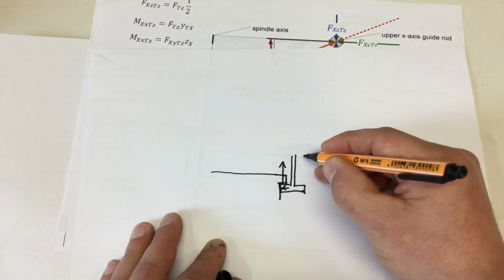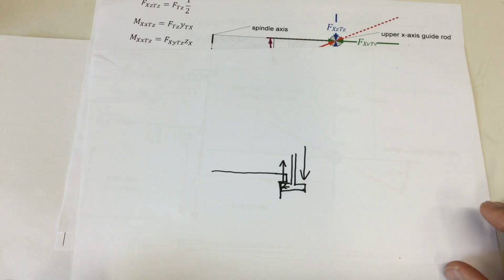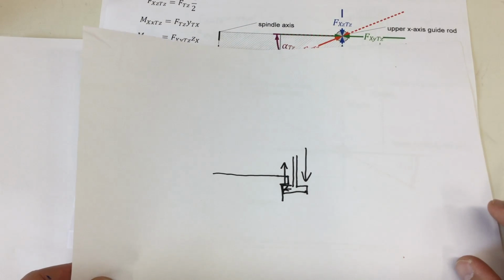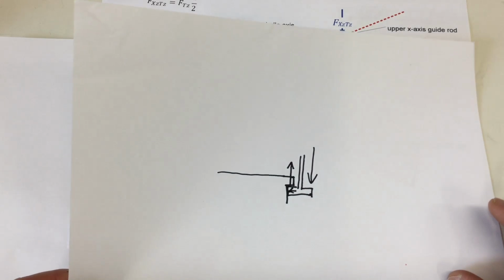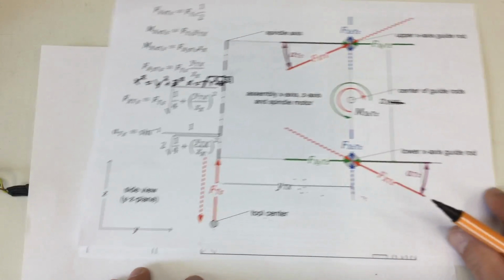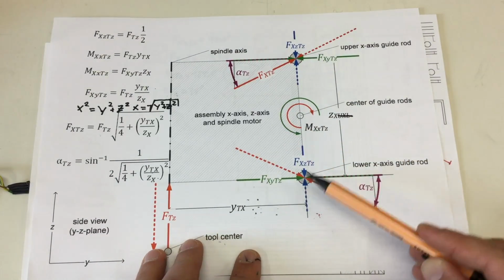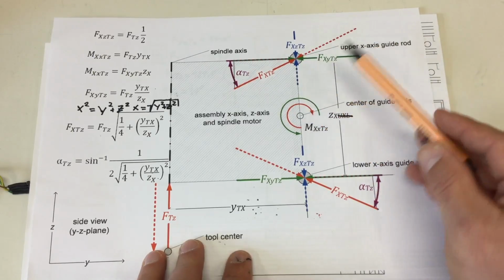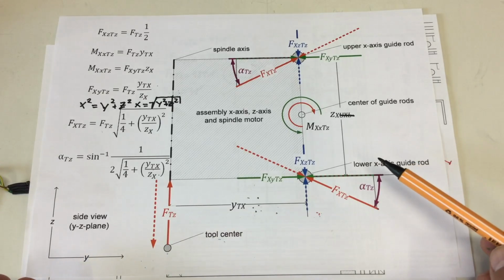So yeah, you can have resulting pulling forces on the z-axis. Not often, but you can. And well, it would be a shame if your CNC machine falls apart if that happens and you haven't calculated for that. So anyway, the dotted lines are the exact reverse, the mirror image of the forces we calculated. The same formulas basically apply.